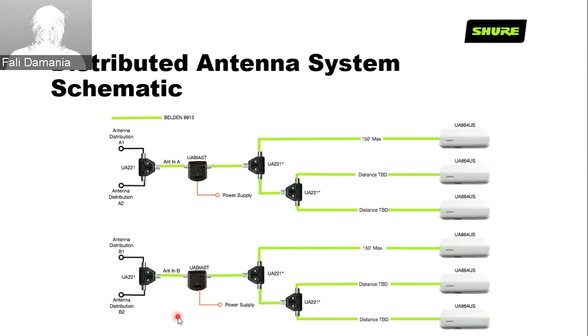So it's not a really easy job. It's something where you'd have to have specifications from an architect or from a designer as to where cable ducts are going and what the wiring is going to be. And then as a designer, it's up to you to spec what is the best quality cable to be used. A lot of consideration. What is the size of the duct? Are there a lot of bends? If there are a lot of bends, how do you accommodate? Do you use a little more rigid cable? Do you use a little more flexible cable, etc.? So a lot of those considerations come in to a system like this.